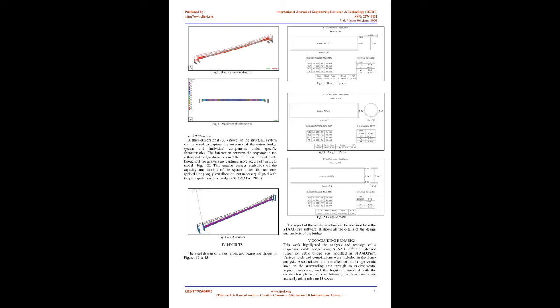C. Load calculations. The dead load is the total weight of all the permanent components of the footbridge structure. These include self-weight of the main cable's deck, steel or timber, cross bracings, side wire mesh, suspenders, handrails, wind guy cables, diagonal stabilizer, connections, etc. The load of a passenger was considered as 50 kilograms. An average of 10 people was considered at a time over the bridge.